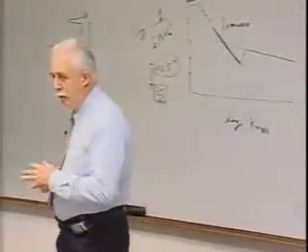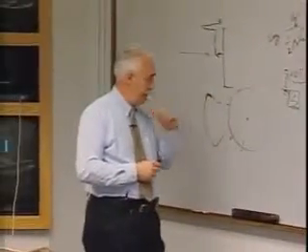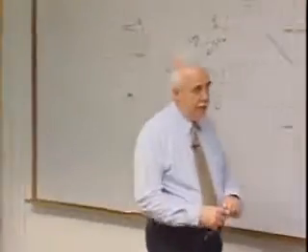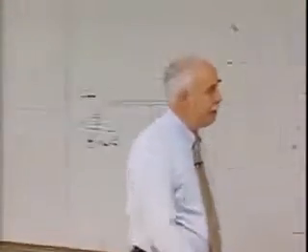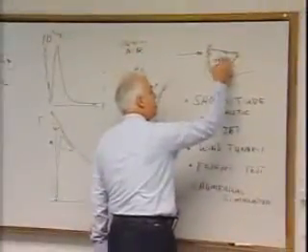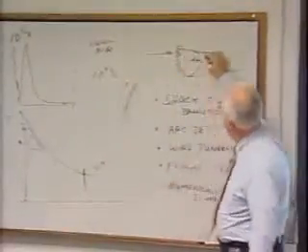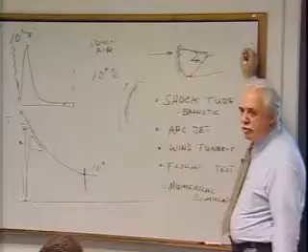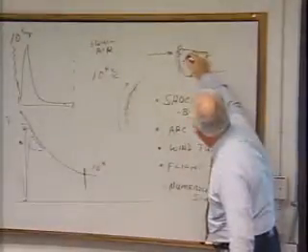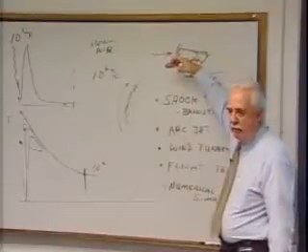and you don't have much control, and I'll address a little bit of that, and you've probably also already heard about the flight mechanics control. In any event, I need some L/D, so I go to angle of attack. In order to go to angle of attack, I have to take the center of pressure, which is basically the point about which the aerodynamic forces act, as if I put a string and pulled on that, and I want the center of gravity ahead of that, and now I've got a nice stable configuration.